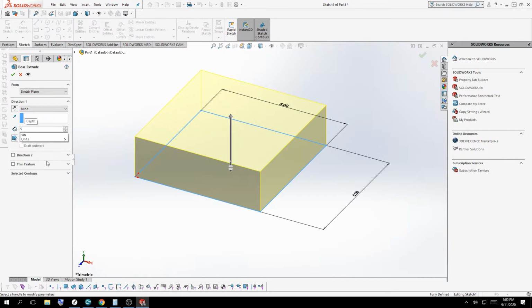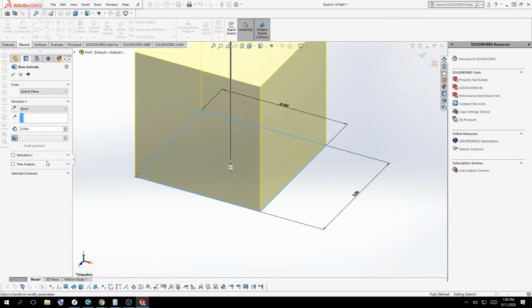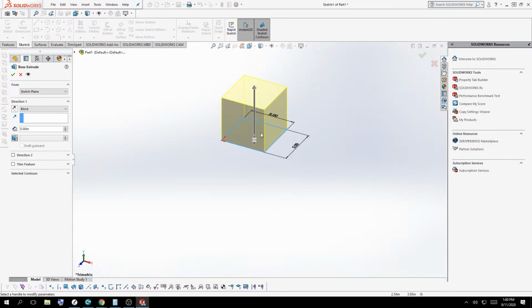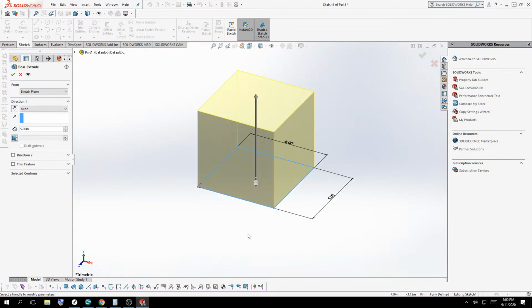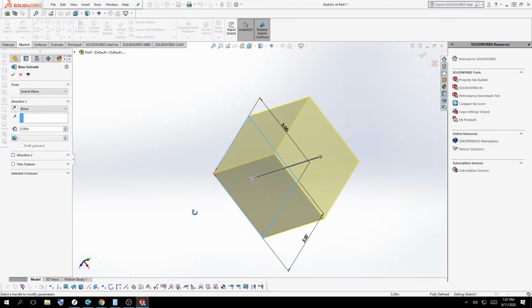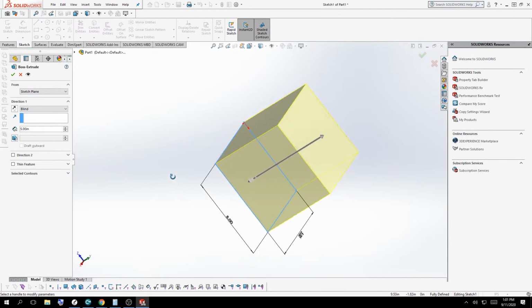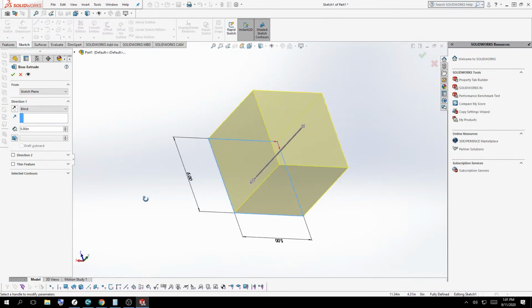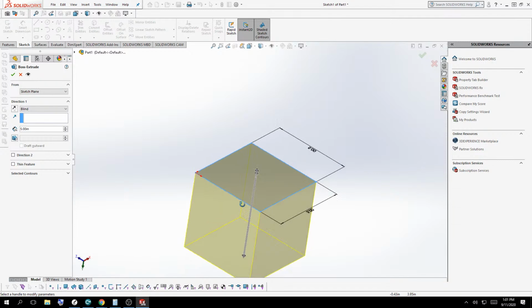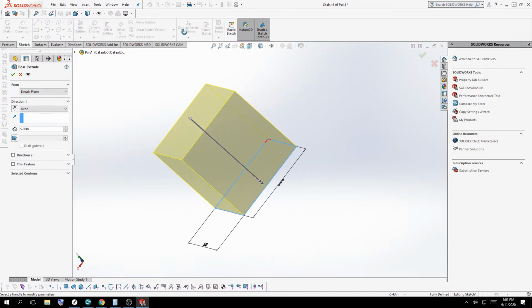Now if you look at the tabulator key or the tab key above the caps lock on the left side of the keyboard, and you press tab and zoom out, you will get a preview. So you can get used to pressing tab, and what it does is it gets your text cursor out of that field, it inputs that value, but it doesn't confirm that value, so you can preview it. If you press your mouse wheel in and drag your mouse, this is one of the few times we drag, you can orbit or rotate your view to inspect to see if what is happening is what you intend. Obviously, if you're following, we have a cube.